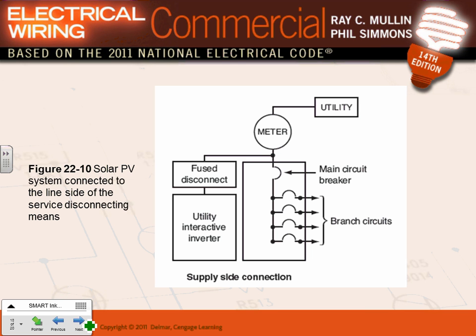The poor man's way, guys, is very easy. Can you guys see the meter here? The meter right in here, this is where Xcel gets you the meter. You can come on the line side of your disconnect. So this is your 200 amp disconnect for your house or for your building. Right on the line side, you tie your power, you put your disconnect here. You have to have a fused disconnect. And then you tie your solar photovoltaic system right at the line side of the disconnect, between the meter and the disconnect. That's called the rich man's way.